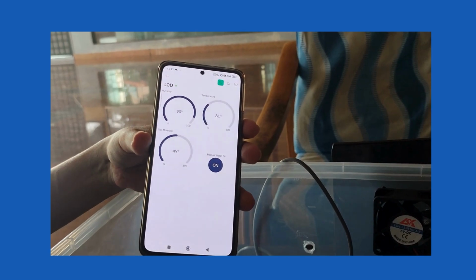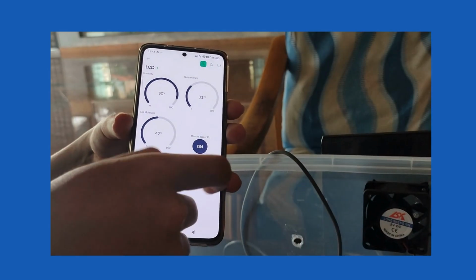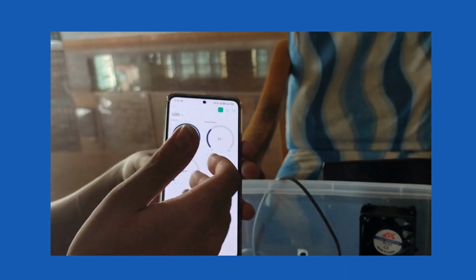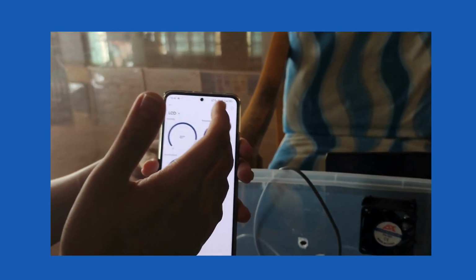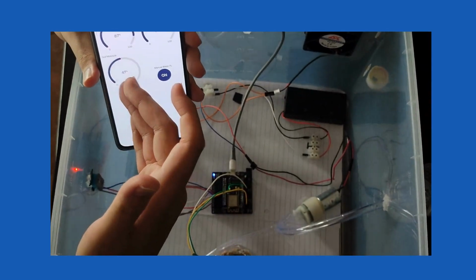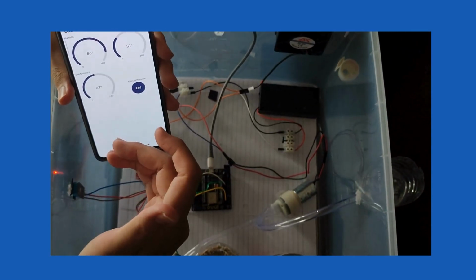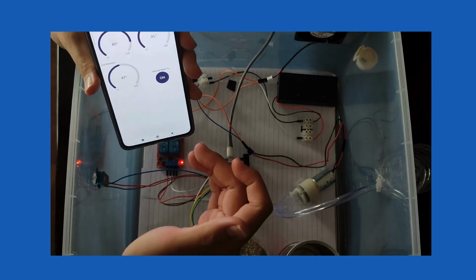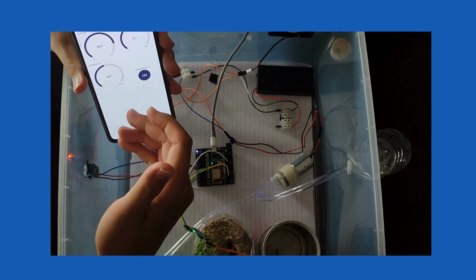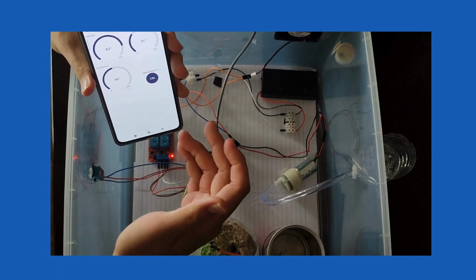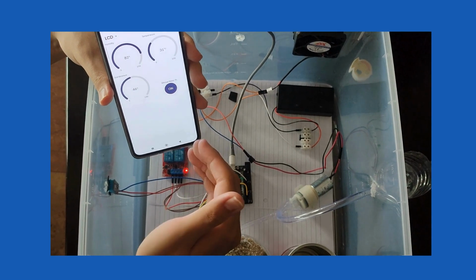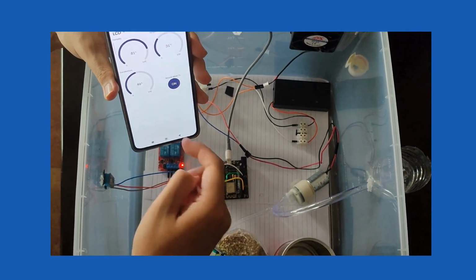As you can see, we also have one manual water button here. You can see this is in on mode. When it's in off mode, that means even though the sensor reaches 32 degrees Celsius, it won't happen, or if the soil is less than 20%, it won't turn on the pump either, because we want our farmer to sometimes use this manual mode for some emergency or critical conditions.